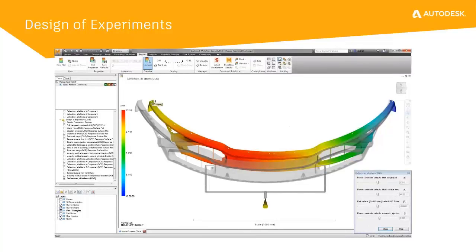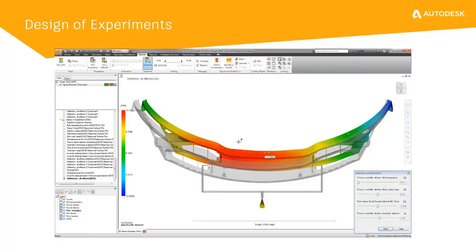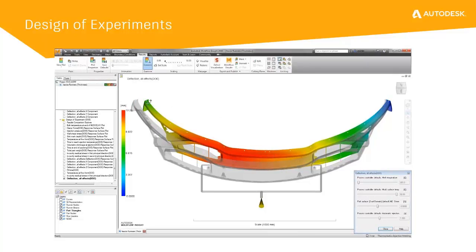There are also other ways to evaluate specific DOE results. For example, this animation plot provides all of the input variables on a sliding scale to allow the user to adjust variables and immediately evaluate the response. Here we can easily see what happens to the deflection of the part when melt temperatures increase or decrease, and the same for mold temperature. This is also important to illustrate the overall warpage trend to determine if changing one variable can actually reverse or impact the warpage trend.